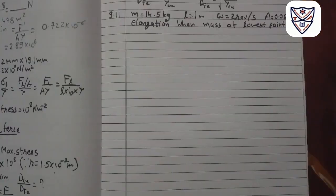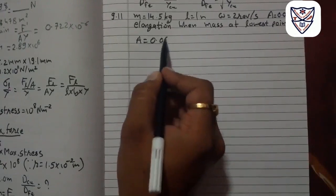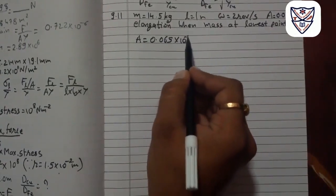In this numerical, we have one mass of 14.5 kilogram, which is fastened to the end of a steel wire of unstretched length 1 meter. So the length is 1 meter. Now that wire is moving circularly. It has angular velocity of 2 revolutions per second, so that is its frequency. And the cross section area of that wire is 0.065 centimeter square. We have to convert it into meter square. So area is 0.065 into 10 raised to minus 4 meter square.